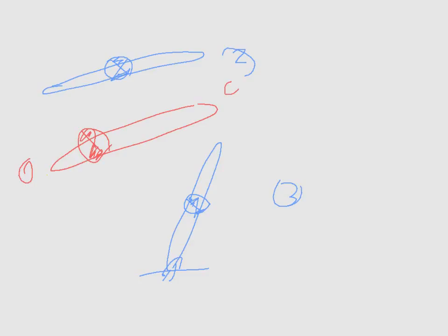So what we'll do here: you know the resultant acceleration of C, and you know its length, OC, and you want to find the acceleration for the centroid. Divide by the distance. How much is the distance? We call it OG. By that you can find AG.